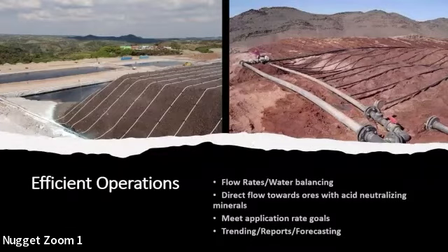And then looking at the surface ponding, the low percolation rates, and also doing some work to look at the ore water solution content, it was near saturation, or high water content. So they quickly identified that, all right, there's poor permeability here. That's the issue. And so they moved forward with a characterization program to understand the hydrodynamics of the ore material that they're mining, and also mitigation strategies that they could use to increase the ore permeability.